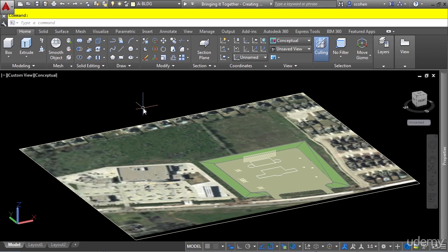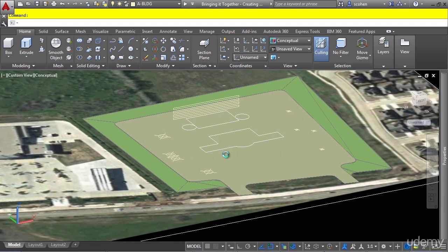Let's bring it all together in a real-world example of performing some mass modeling of a conceptual design of our office park. We'll be creating solids using the press pull command, some extrusions, as well as the subtraction command. If you look in our file, you'll notice some existing 2D geometry that we will use as 2D profiles.